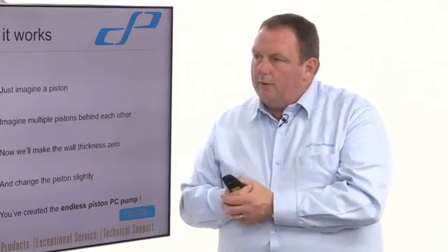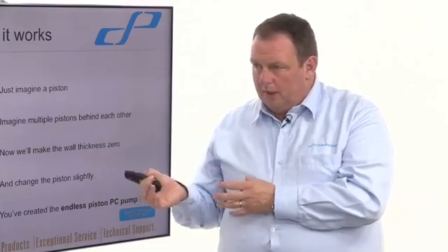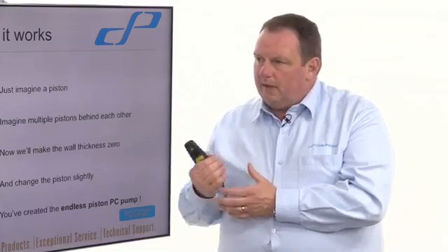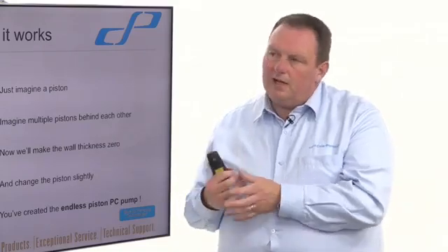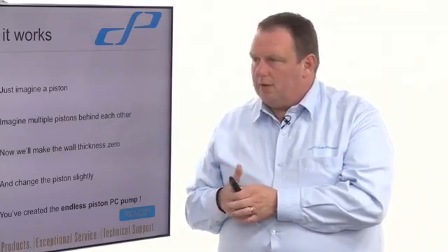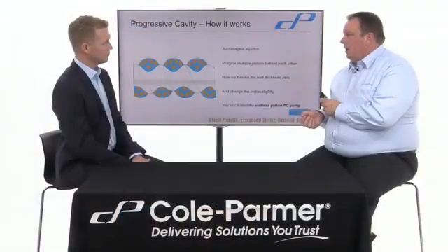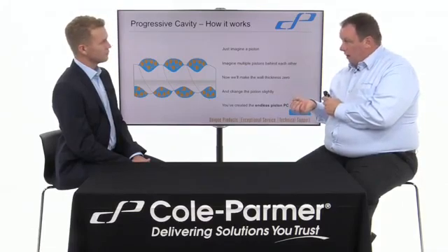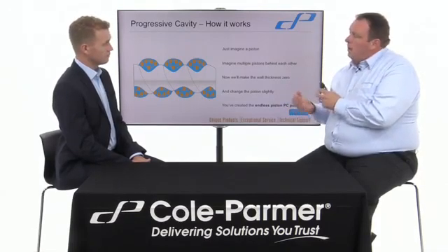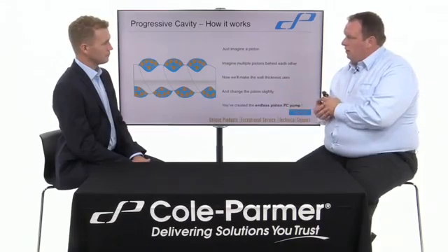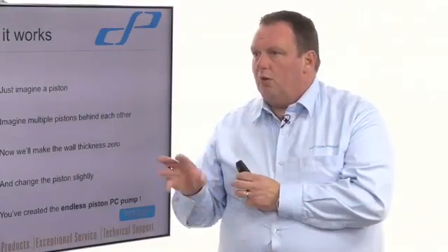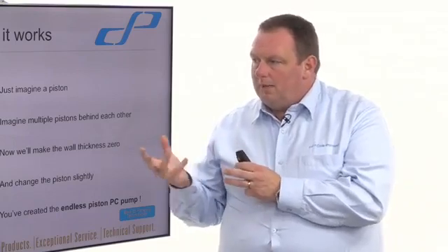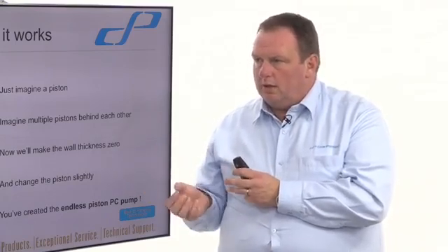Within the food industry, it's very, very effective from being low shear. It's very, very effective as well for a lot of the clay slurries and china clays we use. So a lot of the ceramic ware that's used is also pumped with this. Now, the china clays and things are even more aggressive, abrasive. So they do what they call nitriding on the rotors to make sure they don't wear out. They do many, many different things to ensure they last.